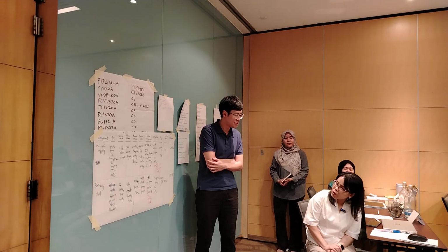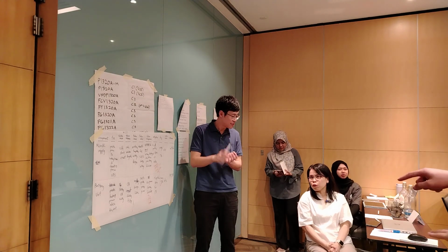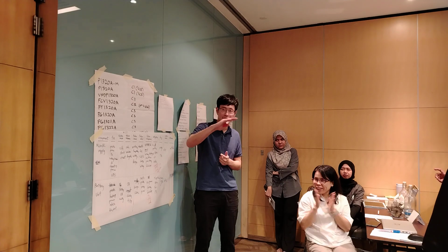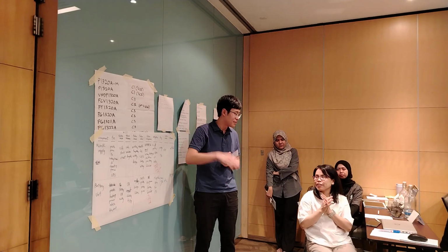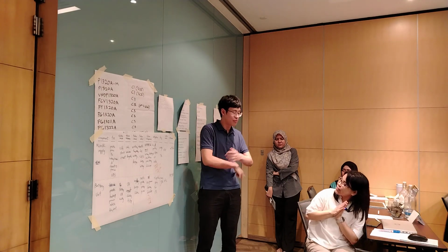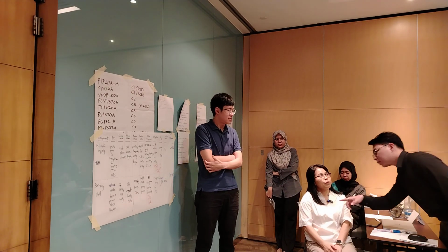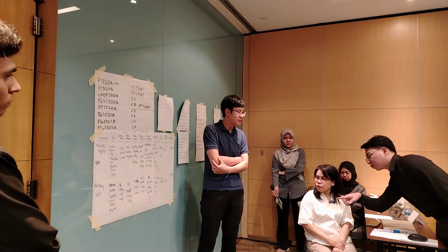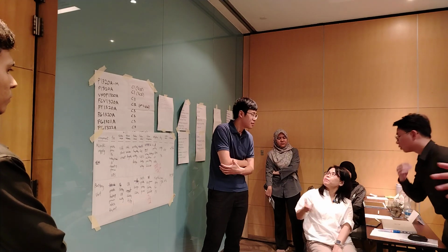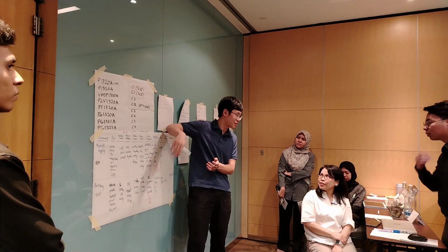But first thing, your circuit breaker is actually open, right? First thing first, what will you check? Check why it opened. Yes, find all the previous history. What's the current? It could be overcurrent, right? It could be a real trip. So the failure mode is the CB40, right? How does your battery discharge test have to do with this? Explain. Battery discharge is only when the battery is failing, which is a little bit outside our scope.